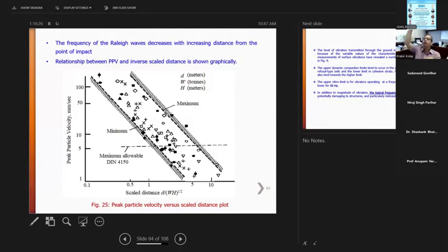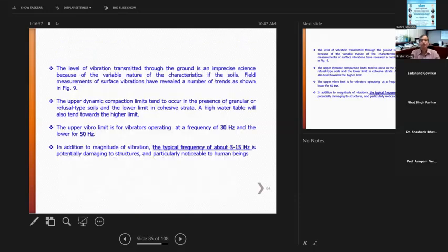So you have huge cranes. Sometimes a huge crane is not available. So what you need to do, the height of fall will be less, correct, in that situation. So you can use the weight of the hammer itself, okay? And it will be the same thing. So how much is the energy, like kinetic energy, right? So W m g H, the simple thing. And then for the peak particle velocity, you need to check how much the velocity travels, and depending on that, whether it is detrimental to the adjoining structures, that will also give you a guideline.